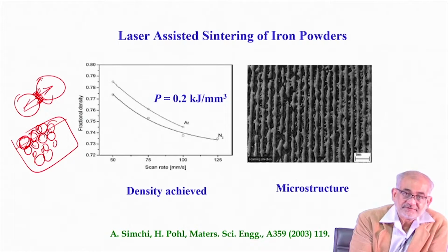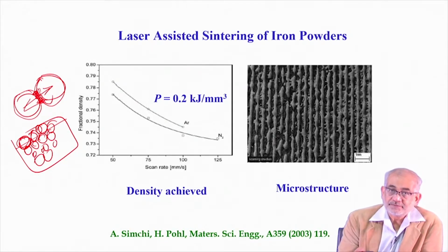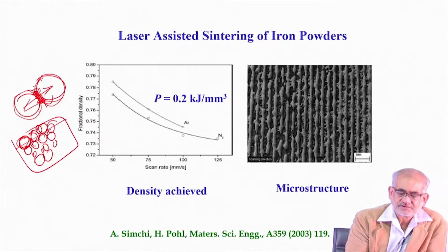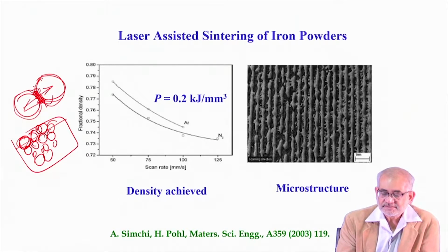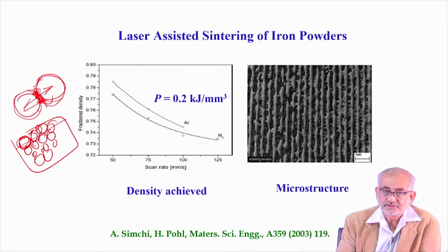The heating effect will be maximum at the surface, and hence the powder particles will get heated such that a thin layer from the surface reaches a fairly high temperature that will allow diffusional bonding to form. It can be solid state, or it can be formation of a thin molten layer, so liquid phase sintering, and this thin layer may form because of a certain reaction, a eutectic reaction at the surface. No matter what, using laser, one can start with powder particles, then sinter and create a bulk solid, the density of which could be close to the theoretical density.